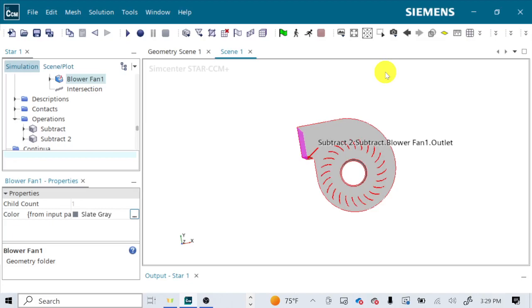We, however, just need to do more work because part of this thing is rotating. Part of it is not. We need to separate the part that is rotating from the part that is not. So we actually are going to have 3 regions. Even though it's all made of air, we're going to need 3 regions. One for the air that's before the rotating part, one for the air after the rotating part.